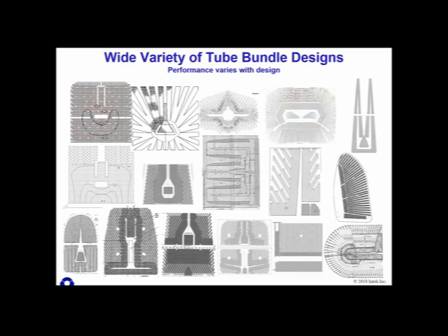And so you would get different material spec'd into the design to tube that region with a stainless steel or copper nickel tube in those air removal sections. So it's not really velocity related or impingement related. That's why you would typically see different tube wall and materials on the periphery. It's for a different reason to have that in the air cooler section.